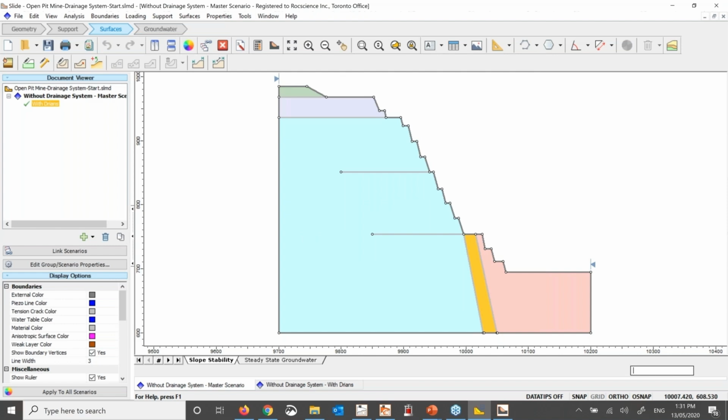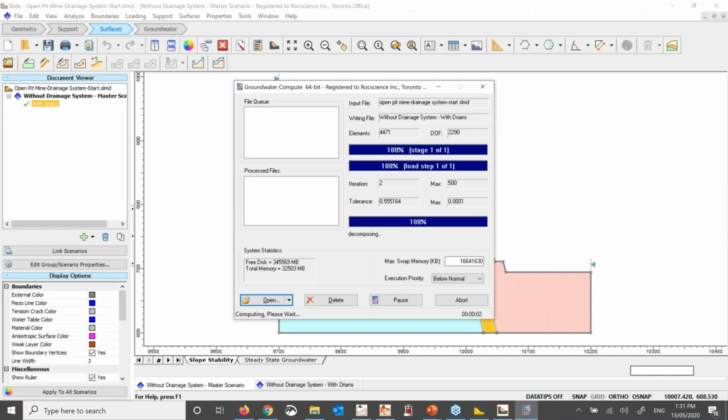Now, this example is rather complicated. All the material properties that we have there are using nonlinear hydraulic conductivities, especially for the unsaturated case. We have so many options for that, like the Fredlund and Xing formulation. We have a simple function that we have developed here, Van Genuchten, all these functions that are used in the literature to define the hydraulic properties. We have them included in the slides.